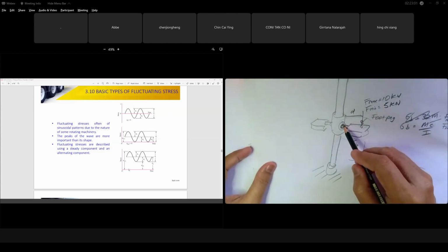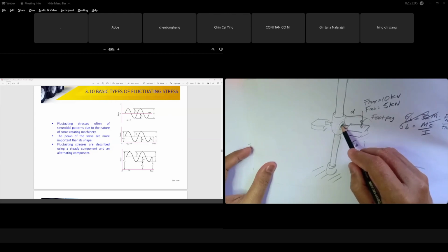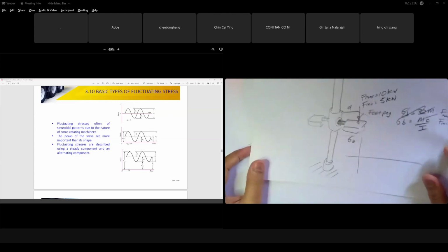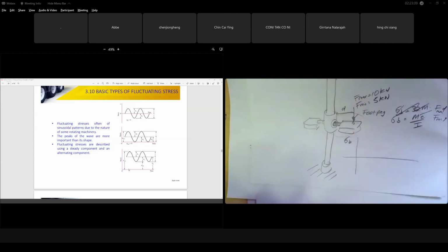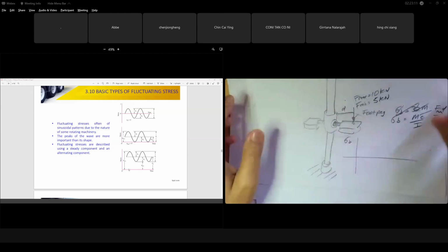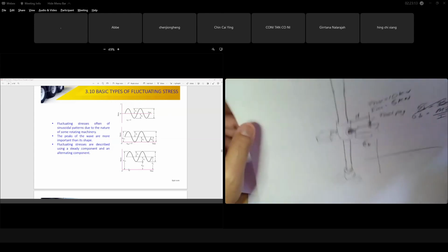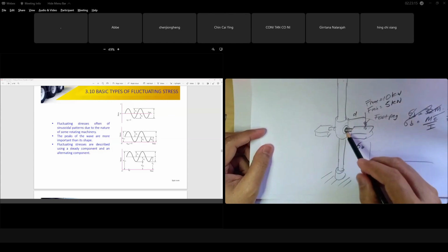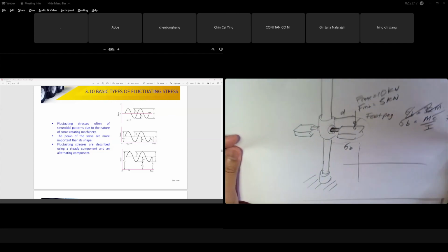Based on our logic decision, of course, because we welded here, we have to study the shaft size too. Is it safe or not? It is fatigue loading because we step on it at the maximum point in time. The loading is no longer static. That is fatigue, so it will weaken. The shaft too, the strength is the S-N.